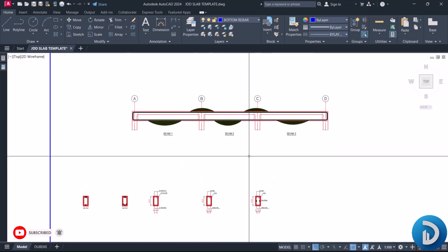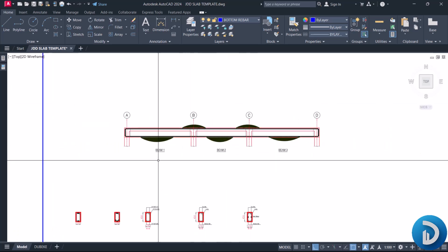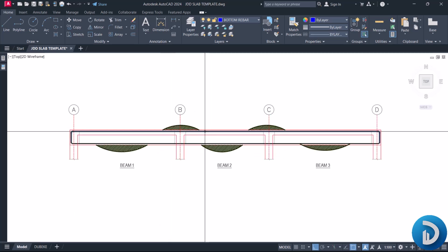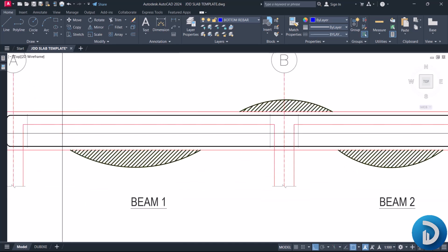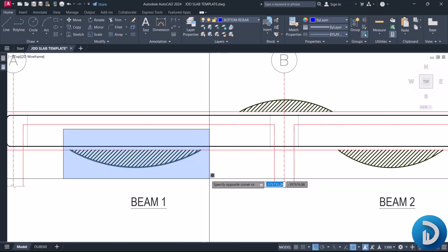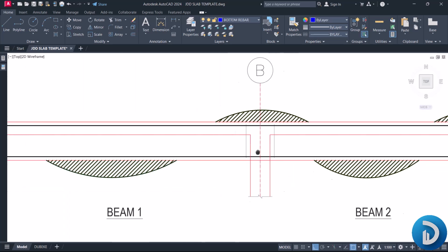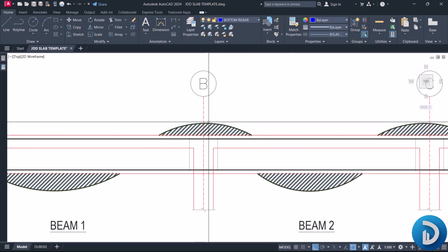Then also speaking about the hanger bars, if we cut a section through a continuous beam, you will agree with me that we'll have a beam moment diagram that looks just like this. We'll have our maximum moment at the bottom here, our positive moment here, and we'll have our negative hogging moment at this support zone.